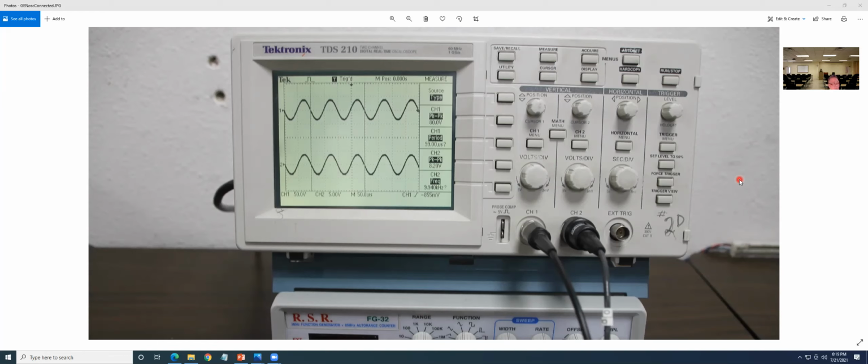whenever you change the signal, like you get 1K, 1 kilohertz, and then you change it to 10 kilohertz, then you must press auto set measure for the scope to update with the new information. Okay? Or when you're changing something in your circuitry, after you make a change, you have to press auto set and measure.